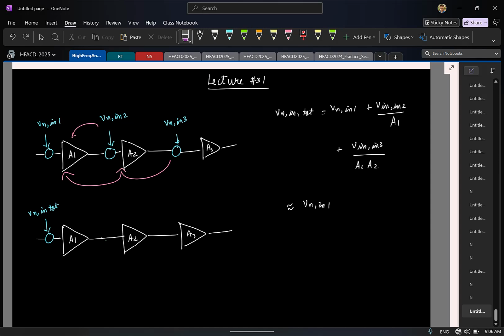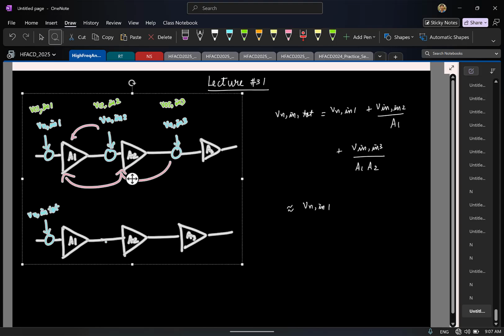Cool. So any questions on this? I guess this is simple enough for you to easily comprehend. No doubts, I hope. And although I looked at noise here, even if you try to calculate the input referred noise, the same result will hold. Again, the offset of each stage you can model using an input referred quantity. Once again, if you model the overall input referred noise, the same result will extend. So that's about multi-stage structures, noise in multi-stage structure and offset.